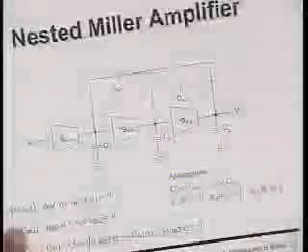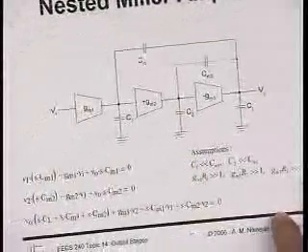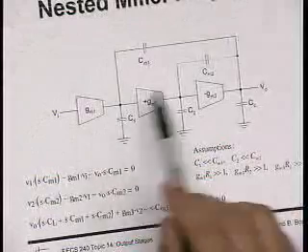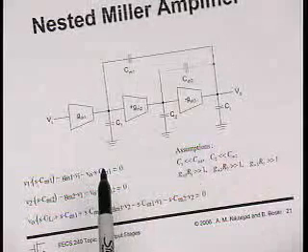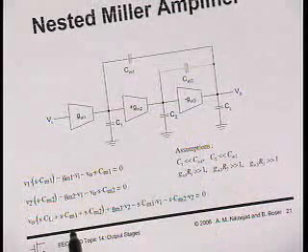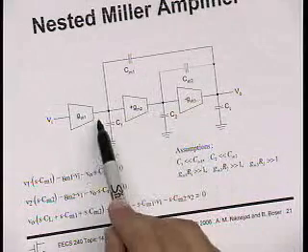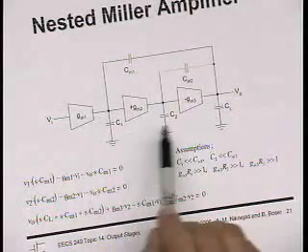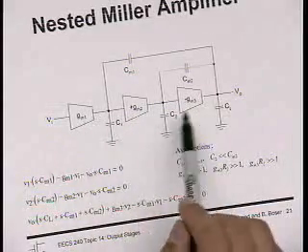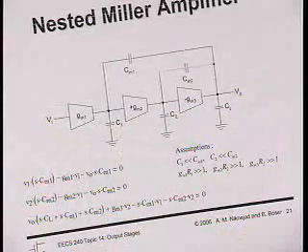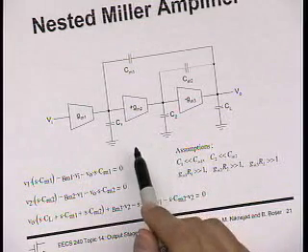The way to analyze this circuit, if you look at Gray and Meyer, they analyzed this in quite a bit of detail. And the analysis here is even simpler. It doesn't give you the exact right answer, but it gives you a good idea. So what we've done here is we've gotten rid of the resistances in each stage. For simplicity, we just assume ideal gm stages with no output resistance. That of course means I have infinite DC gain, and a pole at 0.